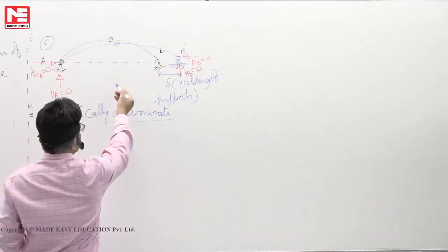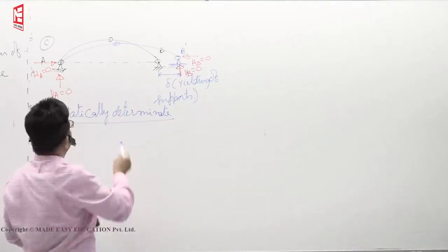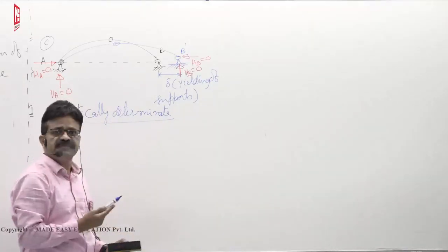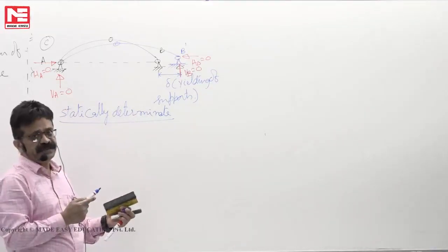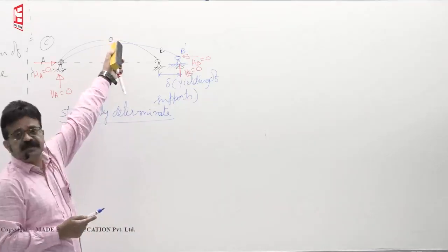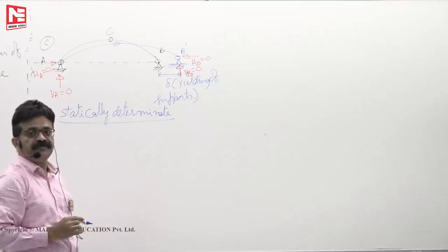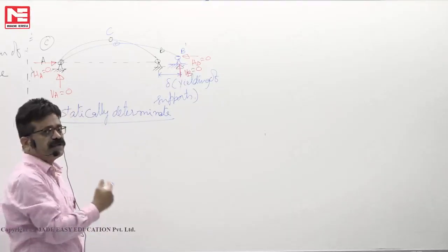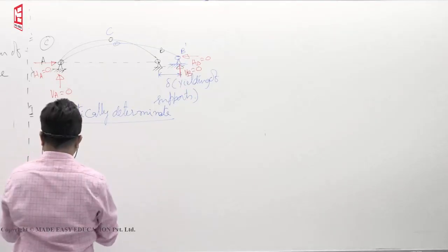But I am now taking for granted that a three hinged arch is a determinate structure because there are four reactions, three external equations of equilibrium, sigma x 0, sigma y 0, sigma m 0. Internal equilibrium equation is bending moment at C is equal to 0. So, four equations, four unknowns. You can find them statically determinate.